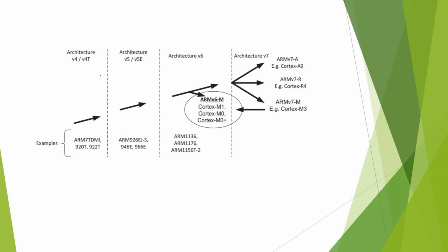Therefore, the instruction encoding played a big role for ARM to enhance their architecture over time, as we can see here. ARM Cortex-M3 is just a processor implementation for the ARMv7-M architecture. ARMv7-M architecture by itself is just the result of the evolution of ARM architecture over time. Before ARMv4, the size of an instruction was 32-bit. On ARMv4 architecture, ARM introduced a new set of instructions called Thumb instructions. Those instructions are 16-bit, so we start to have a mix of 32-bit and 16-bit instruction sizes.